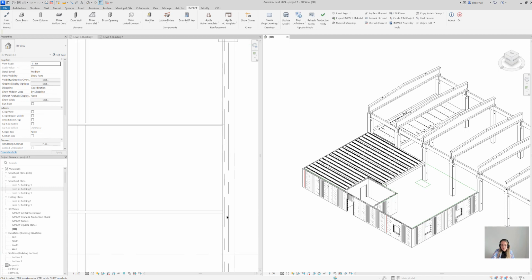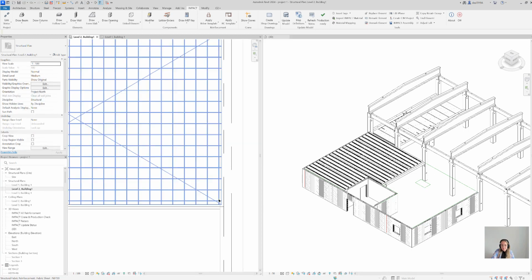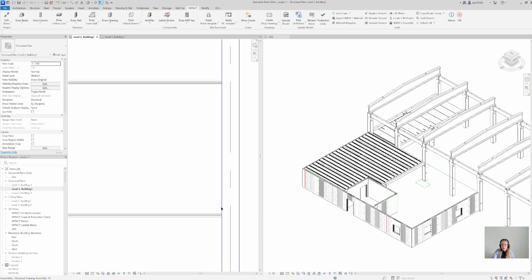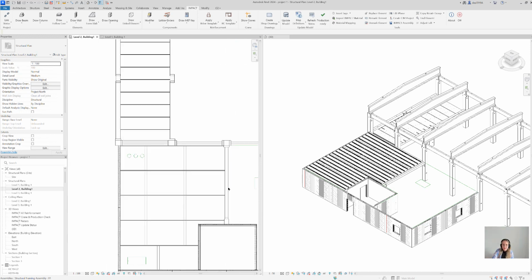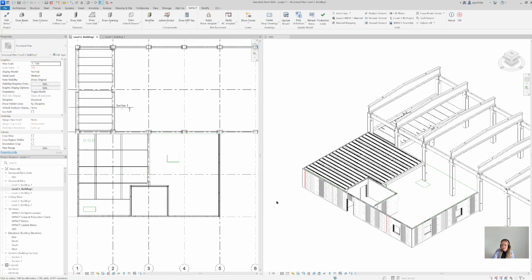What I want to show you here is the support length. If you remember, I set it to 50, so that if your boundary goes here and you say support length of 50, it's actually going to go behind the boundary 50 millimeters so that it can be supported. That's why we call it support length. So that's a pretty smart feature when modeling foam slabs.